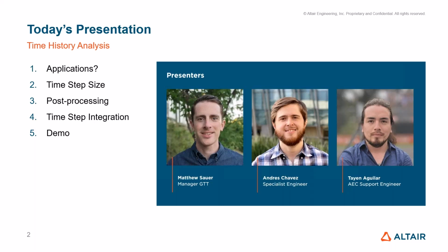We're going to talk about one of the nuances of time history analysis, time step size, and how you can use that to your advantage, but how it can also be to your detriment if you're not paying close attention to the values that you're using. Time history analysis also has some unique aspects of post-processing that are helpful to understand. And there are two different ways to integrate the time steps as well that we'll get into.